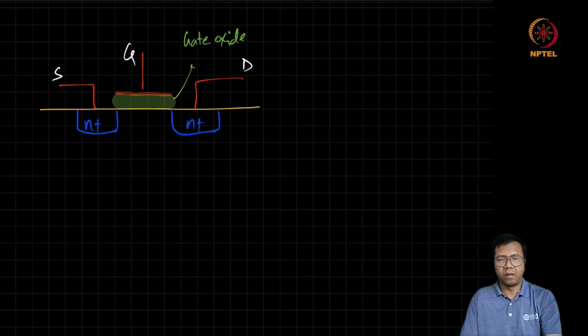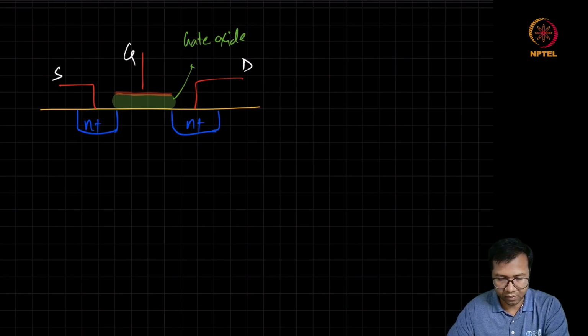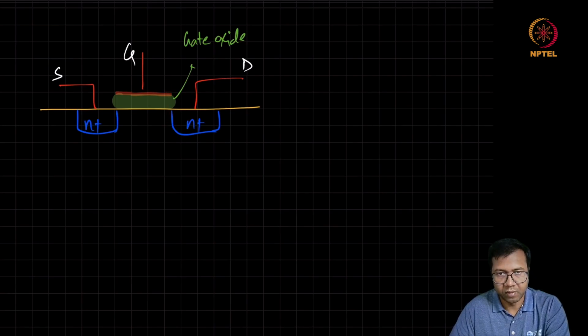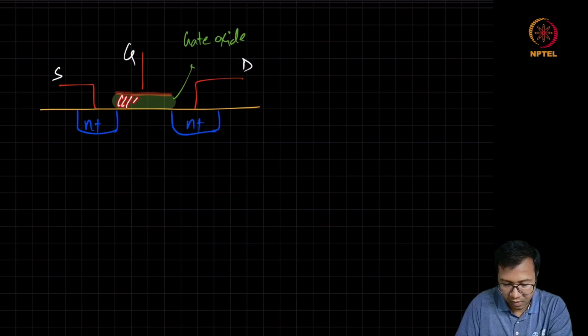The gate oxide will many times be just silicon dioxide, but there are also new processes where this is a specialized high dielectric constant material. This gate oxide can be very, very thin compared to the other interlayer dielectrics. As a result we can achieve much higher cap density when we are using this as a capacitor.